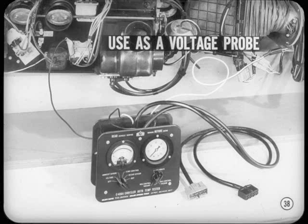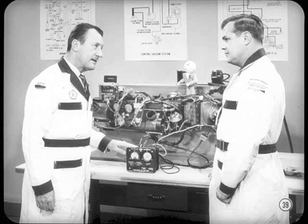You can also use the tester as a test probe to see if a circuit is live. First, unplug the 8-terminal connector. Then ground the white lead solidly and use the black lead to test for voltage at the various switches under the various operating conditions. The operating conditions are as many and as varied as there are combinations of signals from the 2 sensors and the instrument panel selector. It's almost impossible to predict every condition of temperature, so let's look at some basic possibilities.